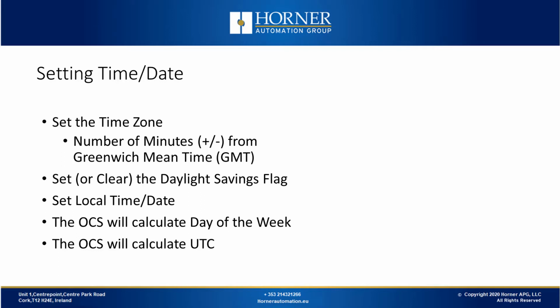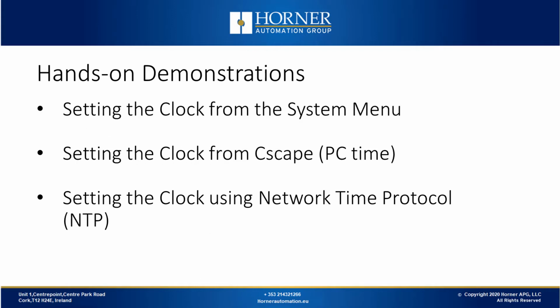Then you want to set your local time and date. We don't set the UTC time and date because customers set up local time in the OCS. After the local time is set, the day of the week and UTC are automatically calculated. Okay, so that's the general process that is followed. Now let's do a demonstration on setting the clock from the system menu, from Cscape, and using network time protocol.